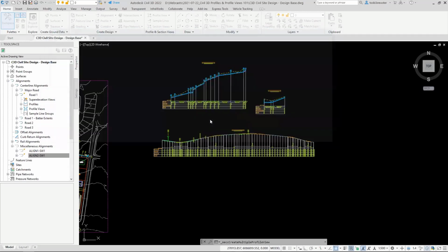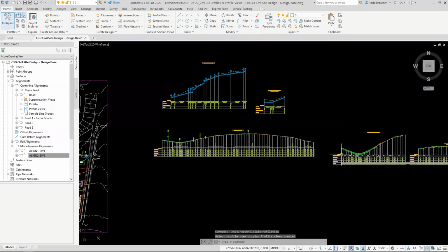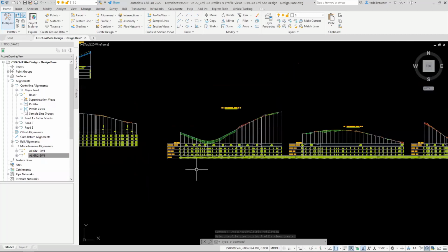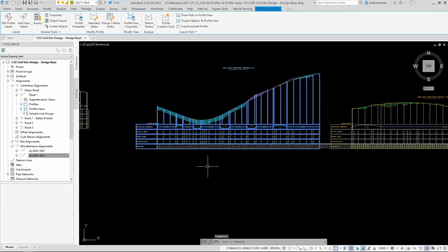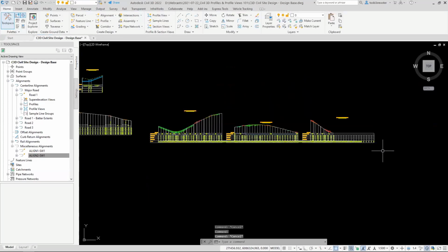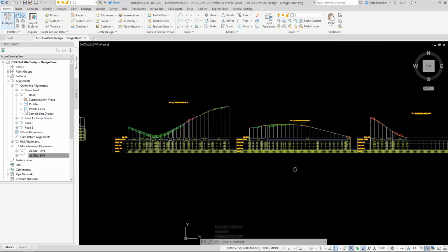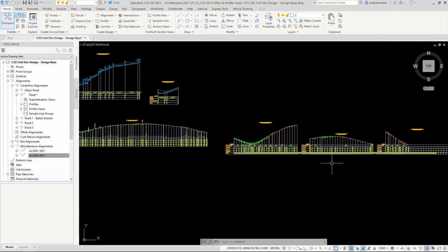And then you go create the views, and you push down, and it will drop in the views for each one. Oh, and I forgot to set chainage profile band style. But anyway, now I've got a profile view for each piece. So it's 250, 250, 250. And then I can refine these to suit what it is I might be wanting to present.